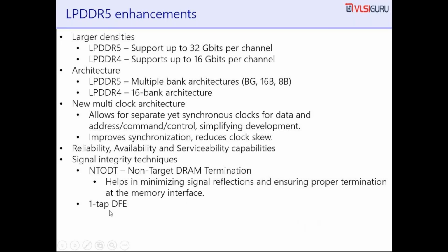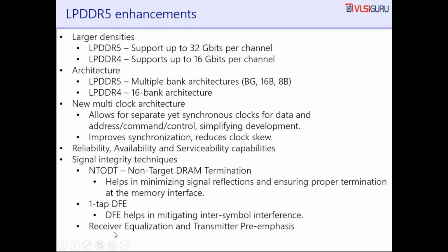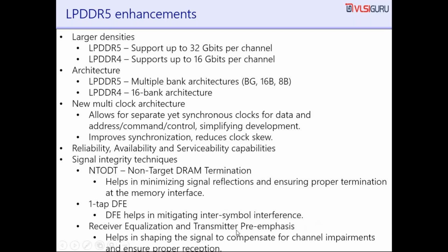I mean, one tap means kind of one stage DFE. DFE helps in mitigating inter-symbol interference. And also receiver equalization and transmitter pre-emphasis features have been added, which help in shaping the signal to compensate for channel impairments and ensure proper reception.